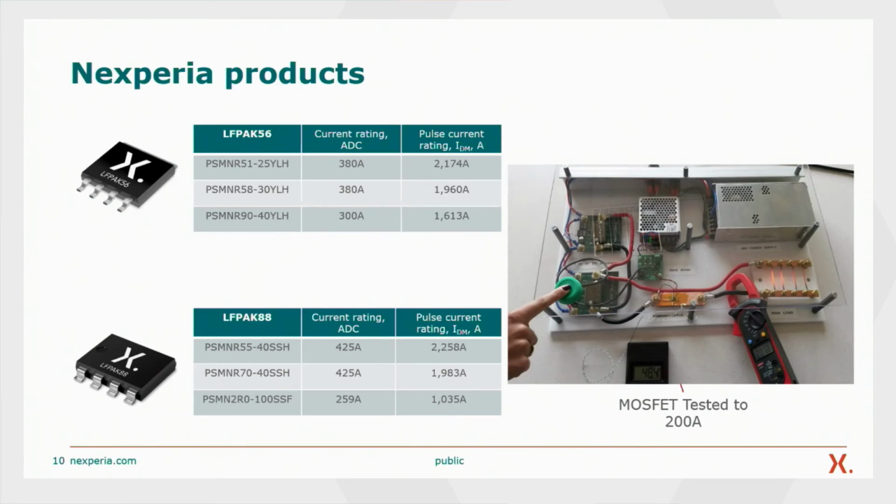As those black wires, which connect to the copper bus bar that the MOSFET is on, start to heat up, they will heat up the copper plate, which would heat up the mounting base of the MOSFET as well. In a real application, we would usually find that it is the circuit's or the PCB's inability to take away that heat which would cause, more often than not, the mounting base of a MOSFET to rise. The MOSFET has a very low RDS on, and we wouldn't expect that to be causing all of the temperature rise. We usually find that the circuit itself can cause the MOSFET to get hot.